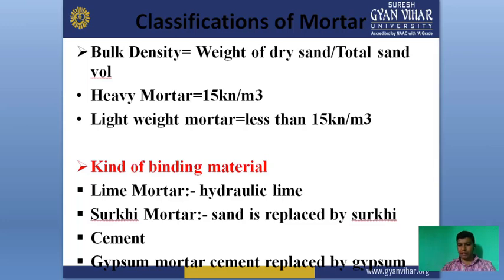The process of adding the cement into lime mortar is termed gauging. The gauging process is useful to improve the quality of lime mortar and to achieve early strength. Due to this gauging process, the lime mortar becomes stronger, more economical and dense. The proportion of cement to lime by volume is about 1 to 6 to 1 to 8. This type of mortar can be used for bedding and thick wall brick masonry work.